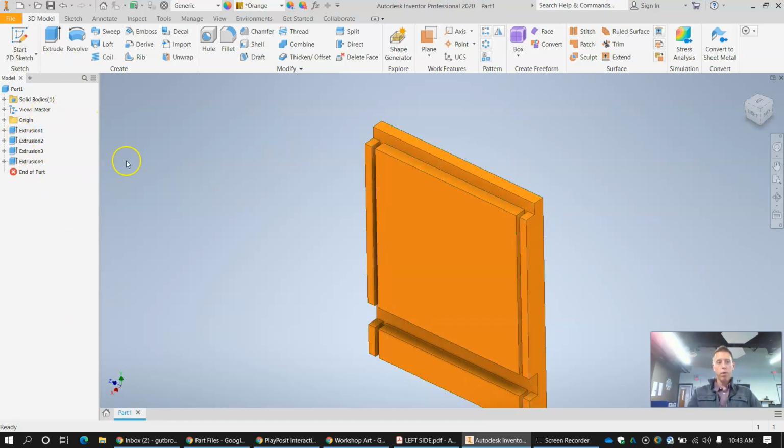That's this white area over here. This is something I need you guys to do at all times. Have these pluses open right here next to your features. Always have those pluses open. So now, I'm not going to click the back arrow and keep going back to remove things I've already done to change those dimensions. That's a waste of time. I'm going to use my browser to go back in time and make adjustments to some of these features.